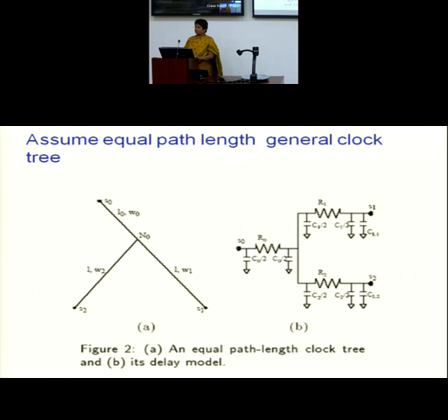Now remember, I am going to distribute my clock signal. I have to design this circuitry because the signal is going to pass through it. The clock signal is going to pass from S0 to S1 and S0 to S2, and we want to ensure that the skew between these two is either 0 or within the bound value. Okay. So now there are two things.